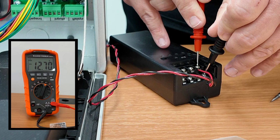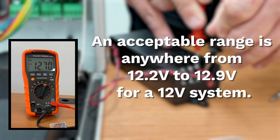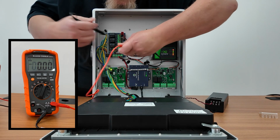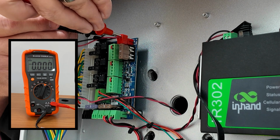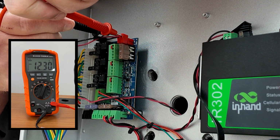For CellGate devices, your meter should typically read between 12.2 and 12.9 volts for a 12V system. If you have a reading outside that range, it could cause significant issues. Anything below may cause a disruption of service, and anything above could potentially damage your device.